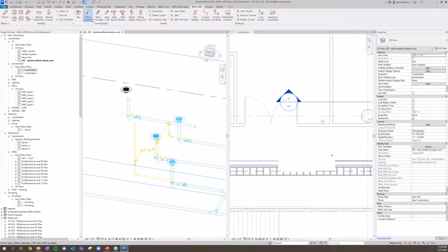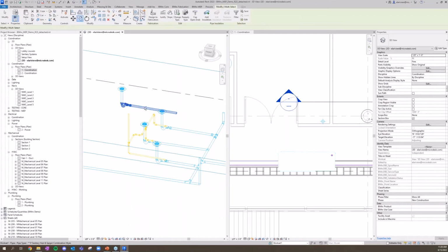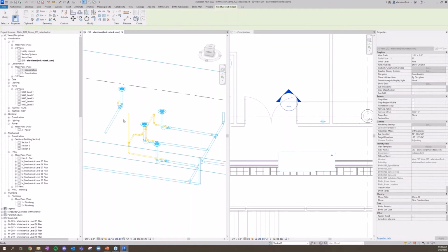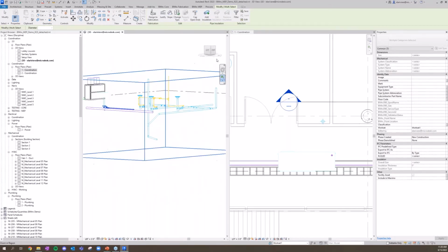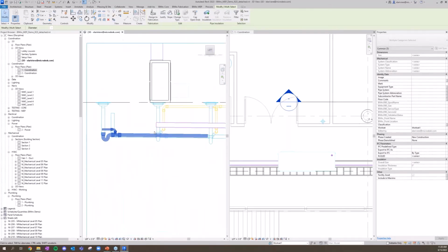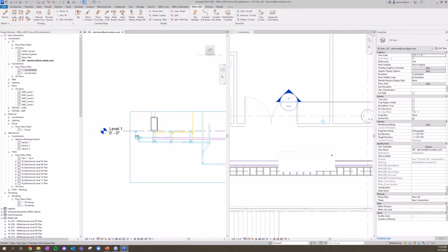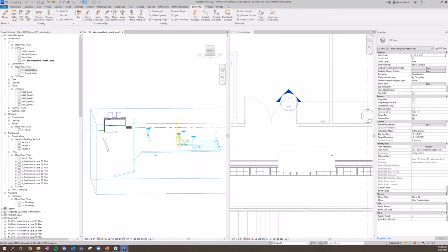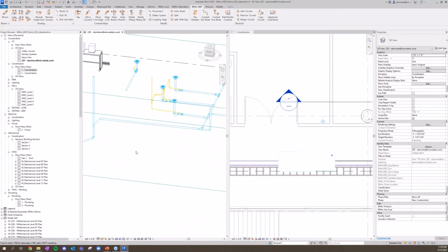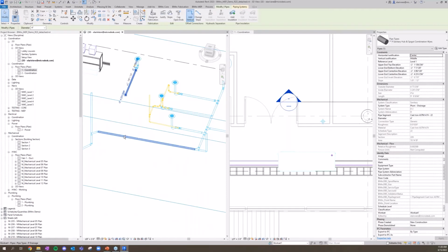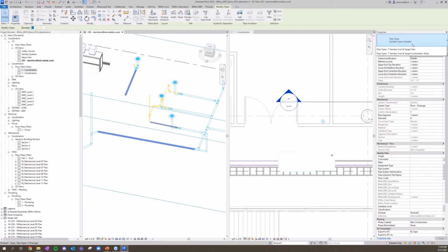Another copy, another move connect. I can go ahead and grab that whole section again, and we have that rotate fitting that we've been using this whole time. 90 degrees over. We learned a few minutes ago, if you go and lock your view, you can lift these things up in only a single direction. So I'm lifting that up, so it's sitting a bit higher than my main over here. And now because my routing preferences are placing Y with an 8th bend, I'm going to very quickly choose an element that does not have Y with 8 bends.